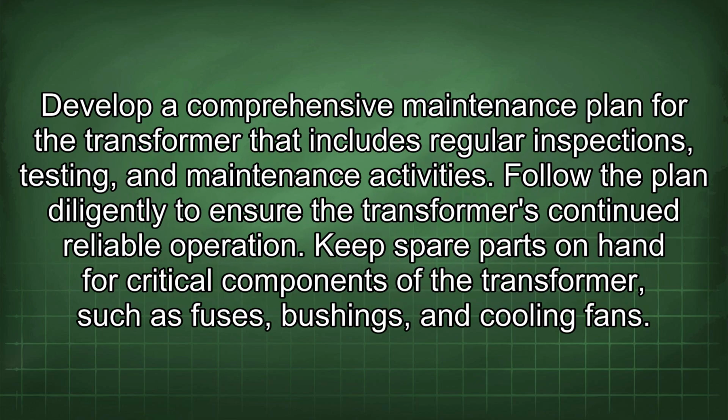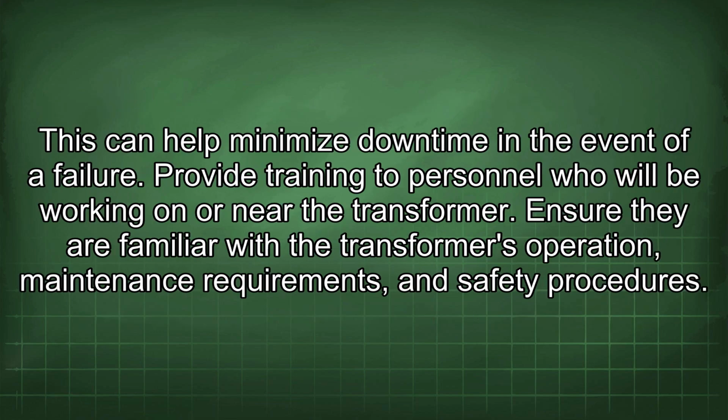Develop a comprehensive maintenance plan for the transformer that includes regular inspections, testing, and maintenance activities. Follow the plan diligently to ensure the transformer's continued reliable operation. Keep spare parts on hand for critical components of the transformer, such as fuses, bushings, and cooling fans. This can help minimize downtime in the event of a failure.